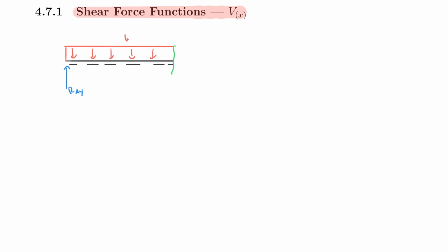And when we do that, we of course always bring in our internal forces from our study card. So we have first the moment, we have the shear force, and we have the normal force, which in this case you can already tell is equal to 0. But these are my different internal forces, which now I have to solve at that cut.